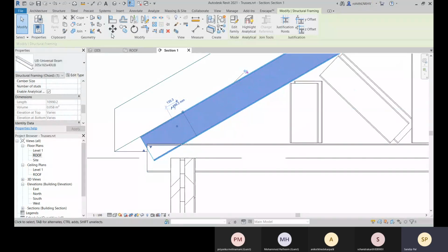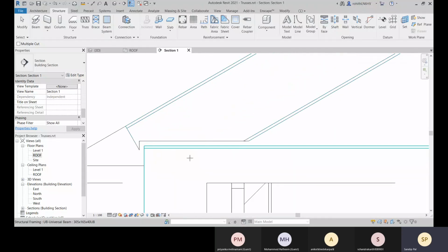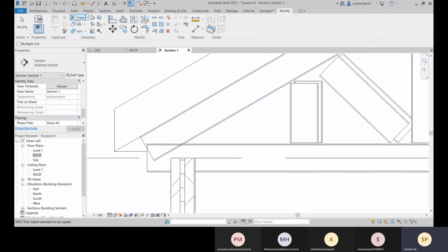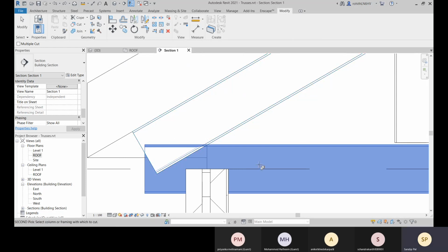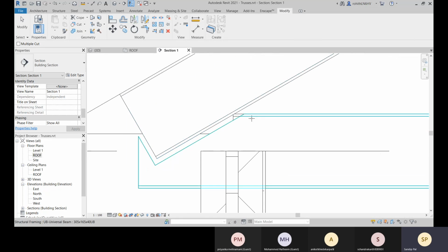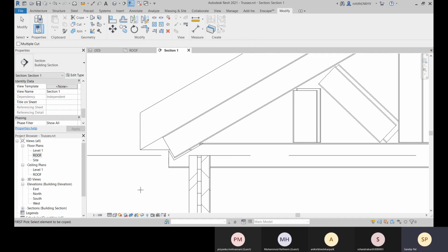And what you can do is you can cope it, apply coping. So here you can do it. So this one and this one. So this kind of things you can do. Okay. So simply you just go to modify and cope, and this one is selected first, or you can select this one as first also. So which one you want to cope, you will be selecting that first, and the other one. So here we have. Okay, so that you can do it. All right.